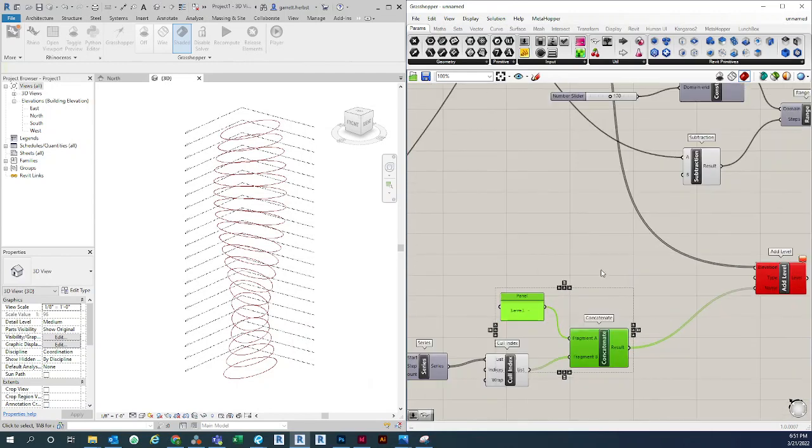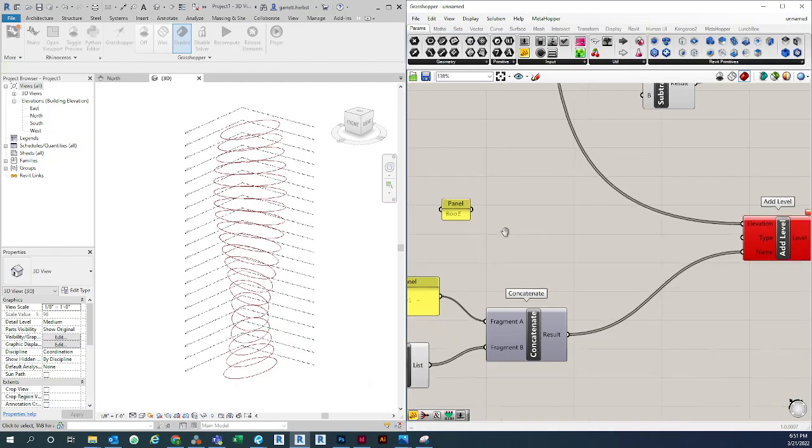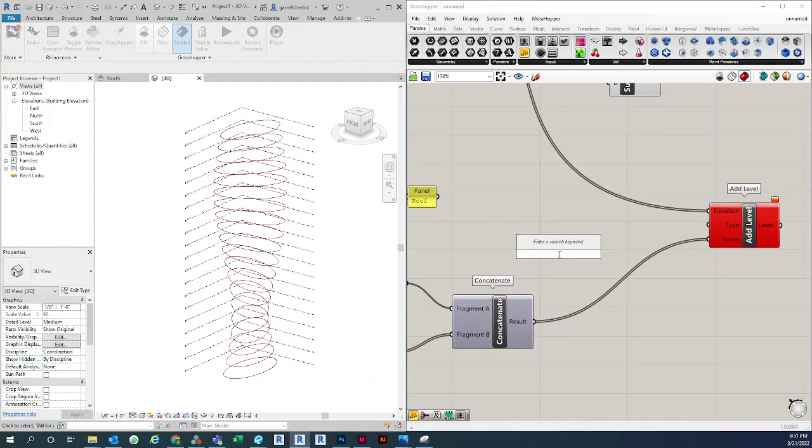We're going to add the text roof. So if you type in a panel, or for a shortcut, if you hit backslash and then type in roof, it will create a panel with roof already in there. And then what we'll want to do is an insert items component.